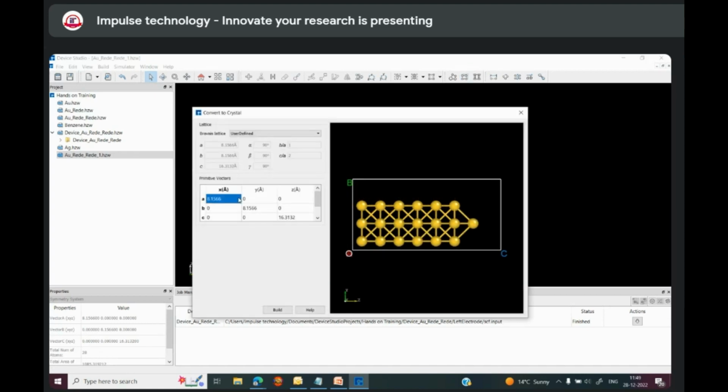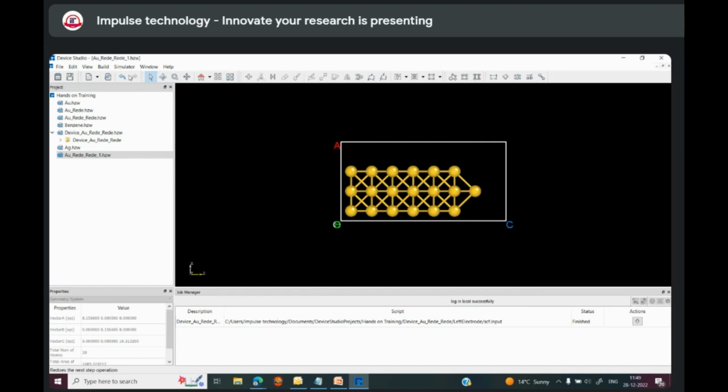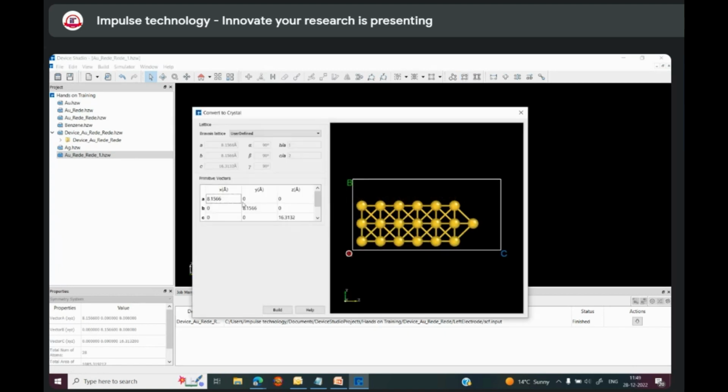Sir, one question, how do we deselect a particular atom? Just a moment. That is how you made the tip, by deselecting a particular atom. Yes, you can select all these atoms, and with control you can deselect this one. Control left click. Then you can click on delete atom. And suppose you want to create a vacuum inside this unit cell,